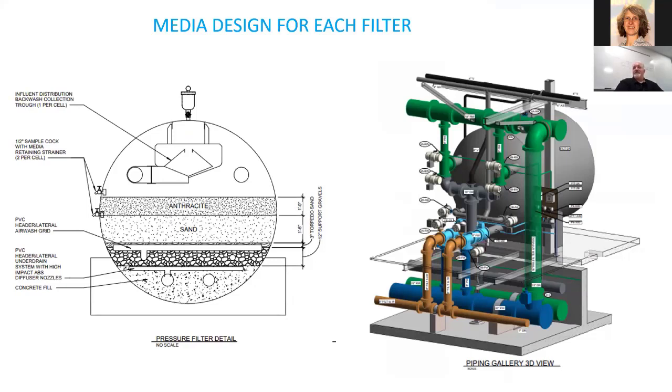The influent is shut off, and valves from the light blue to the brown are opened, and the flow is reversed through the filter. Gray pipe, it comes out in brown pipe for waste. And there are two different cycles, there's a low flow cycle, and there's a high flow cycle.